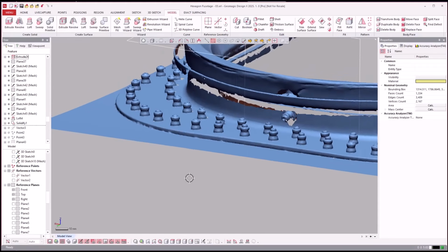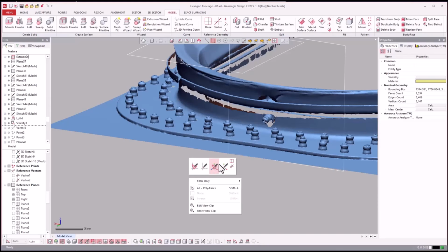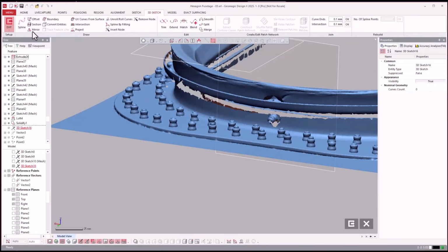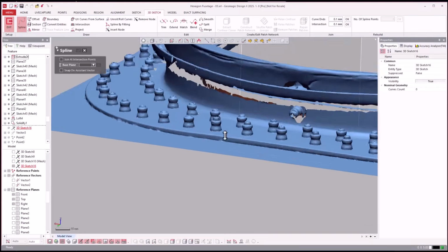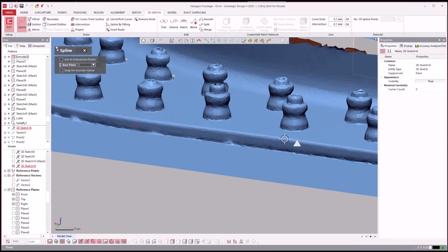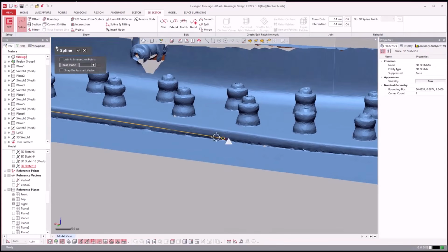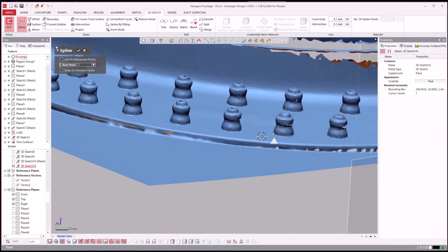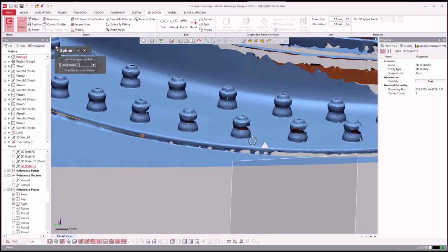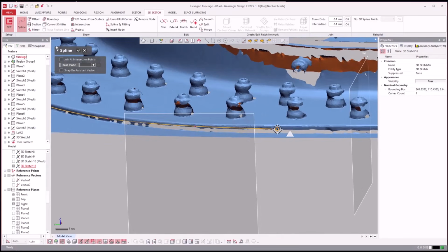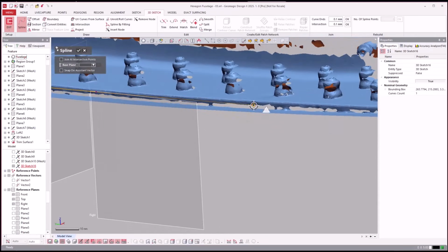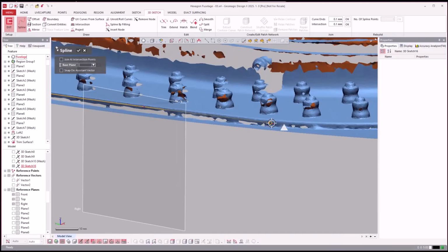Another way, kind of a shortcut, is if I come over to that same 3D sketch tool that I was talking about before, and I come over to spline, and I just come in and click. Sometimes I can do this faster than creating a region on the side, especially when I'm missing data like this. So what I did here is we just went around the entire thing. I'm just trying to go fast so I can get it all the way done.